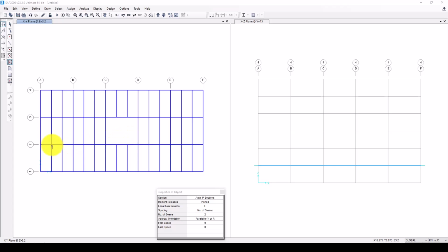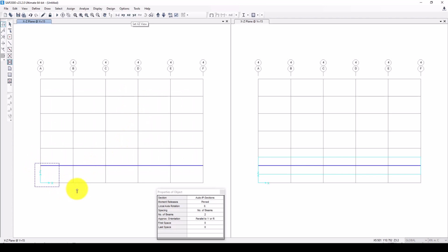The next thing is that let's go to draw the columns. So we can go to one of the elevations. So let me go to elevation 1. I can go to here, YZ or XZ and YZ. If XZ is this one and YZ is this one, so I'm going to use XZ, and here I can select all this. Sorry, it's not primary. We should go back to this one, the first one, again, an IPE section.